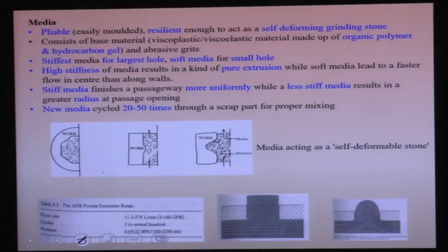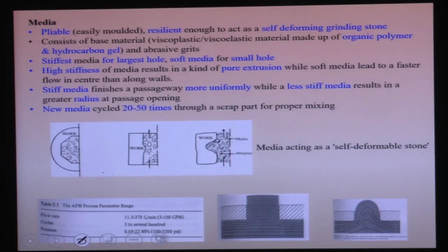This media consists of a base media. This base media is a viscoelastic or viscoplastic media made up of organic polymer and hydrocarbon gel. With this base media you have to add abrasive particles to make the media. These abrasive particles have to be homogeneously mixed with the media.